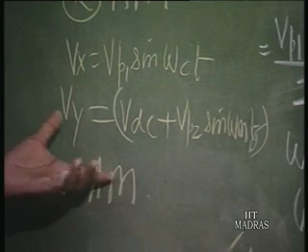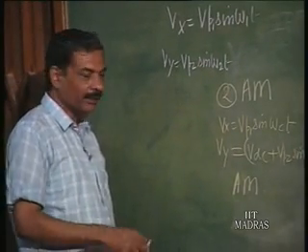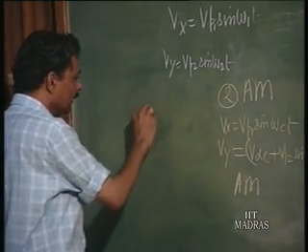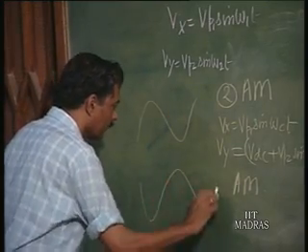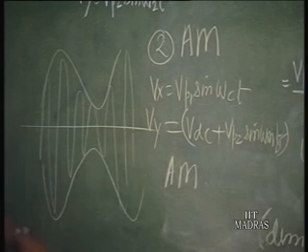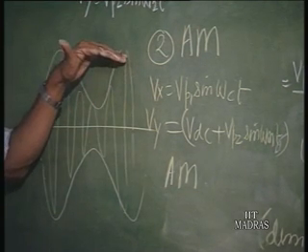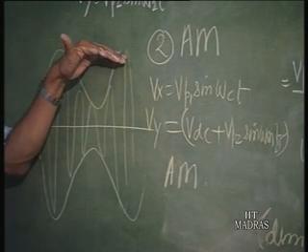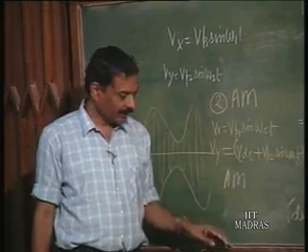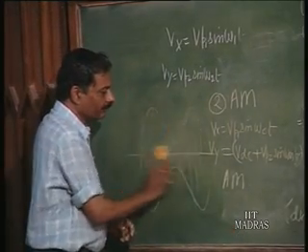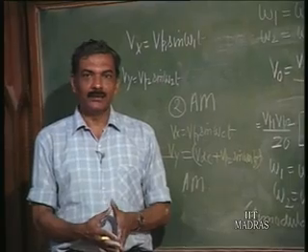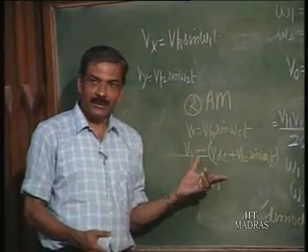So, if you have a non-ideal multiplier, you can obtain an amplitude modulated signal. What is the advantage of an amplitude modulated signal? As against DSB, you can detect this simply by envelope detection, which is done simply by using a diode. The amplitude modulated signal looks like this, that is the envelope, and the envelope contains the full information. Therefore, you can chop this off using a diode and then put a filter so as to detect only the envelope. That detector is a very simple detector, does not require generation of a local oscillator frequency which is as stable as that which is transmitted. So, this is AM generation. AM generation is also possible with the same multiplier. Only thing is that the multiplier need not be ideal, it can be a non-ideal multiplier with x feed through or y feed through component.